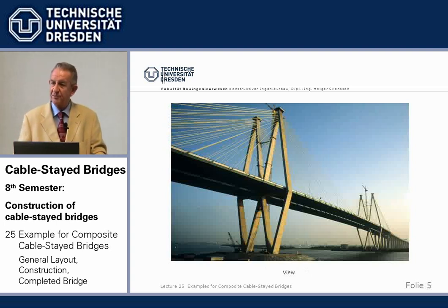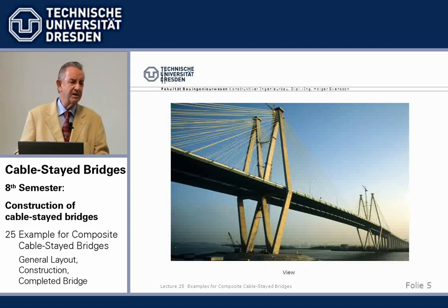Of course, the amount goes somewhere with the square of the span. And later on, it was proven that the 2 independent beams are aerodynamically more stable than any individual beam. So we decided not to connect them, again, to save steel, because we were in a hard competition.